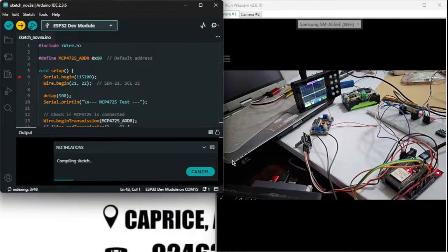If you can see my waveform properly, you can see that my waveform is a bit messed up. So this is where I can do my tuning properly. Let me see where it is on 100. Okay, so now let me increase the time base. Let me increase my voltage so that I get it. Okay, 1 volt will be okay. And to see that if my